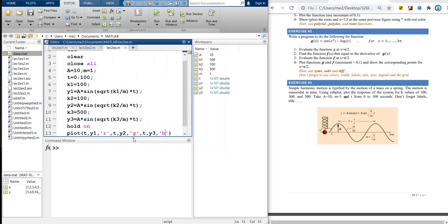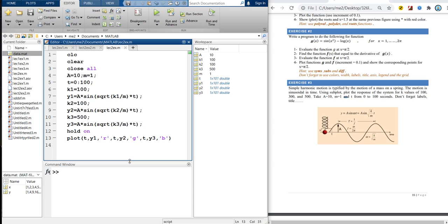So it's better, guys, to do what? We want one figure, but split the plots by using the subplot function. So I will remove the hold on, no need for it. Now I will use subplot. The plot will be like a matrix, or an array of plots. Say how many rows we have: I want 3 rows, 1 column, the first plot, and then I will plot.